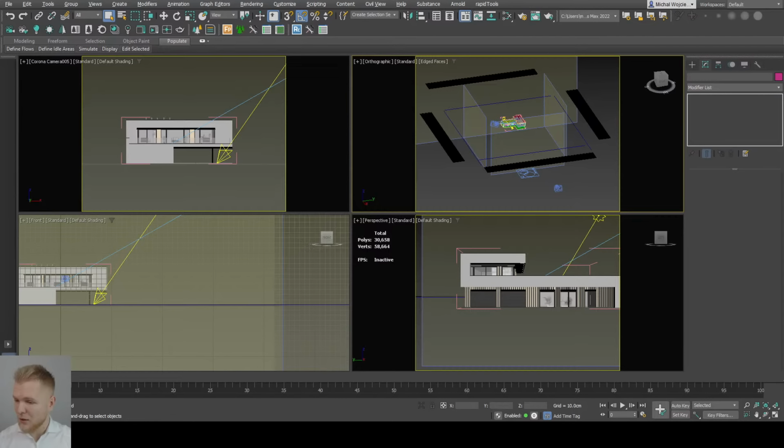How can you make a real fire for a candle or a chimney? So there are many options on how to do it. The easiest one is to simply use Corona light material, which we luckily created a video on our YouTube channel about, so go ahead and visit it right now. So you combine a fire texture with opacity texture and you add it to Corona light. That's the easiest and fastest way of doing it.